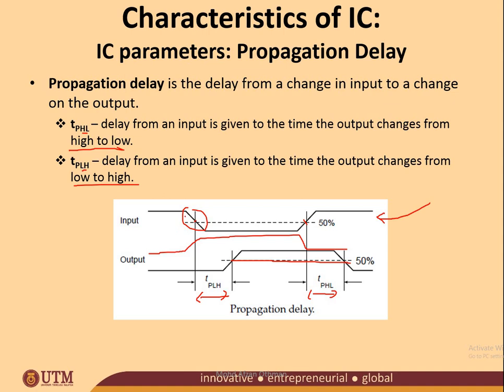They are on the same time frame, but this is impossible because there will be propagation delay for sure. It's just whether it is significant or not. We normally want low propagation delay. If the circuit has shorter propagation delay, the circuit will operate faster. So this is logical enough.